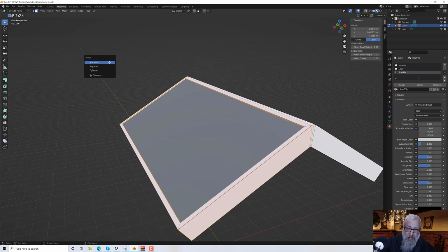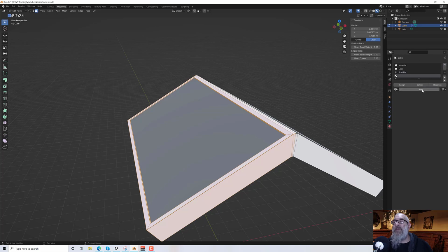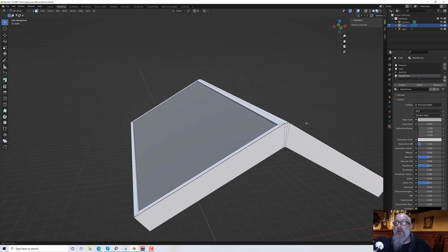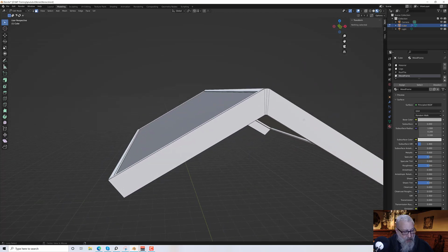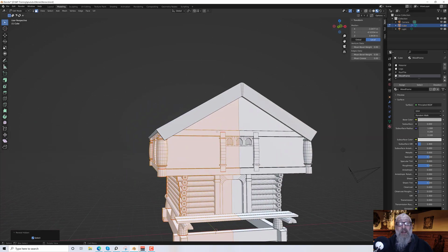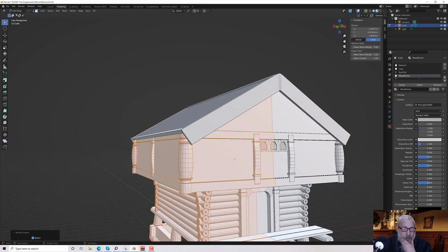And then press M, sorry not M, I'm in Modo again. We'll create a new material, click new, and this one is going to be kind of a wood frame which will share space with other bits of wood on the model. So let's give that a slightly less grey and assign to the selected polygons. There we go. Okay, so Alt H to unhide, and that's put a little bit of detail up there, nothing too much. And now I'm going to come down to the next area. Okay, so we'll do that in the next little section.